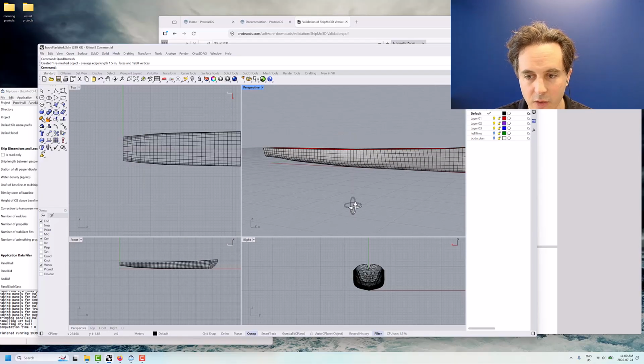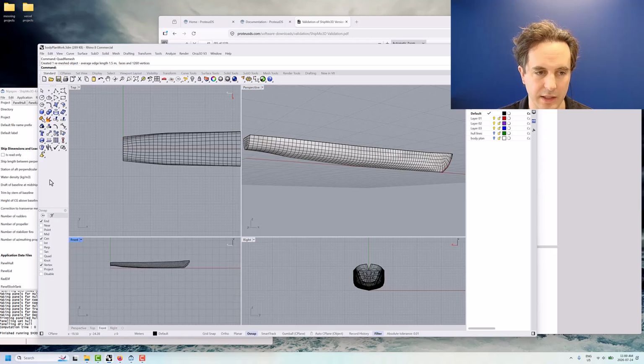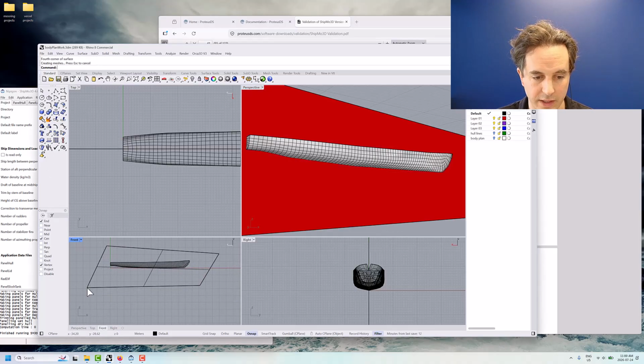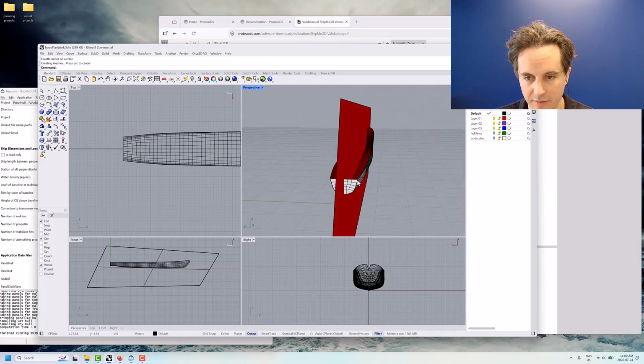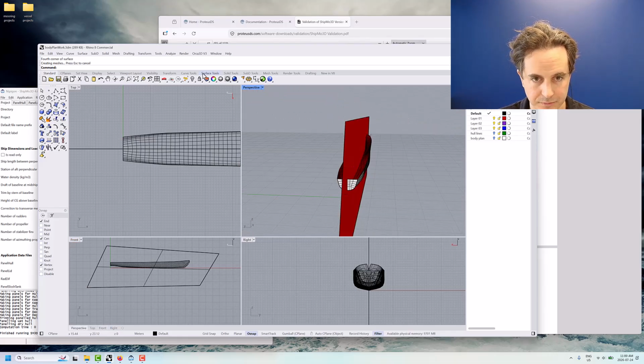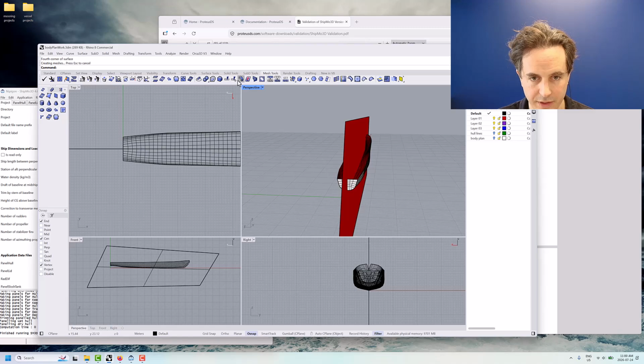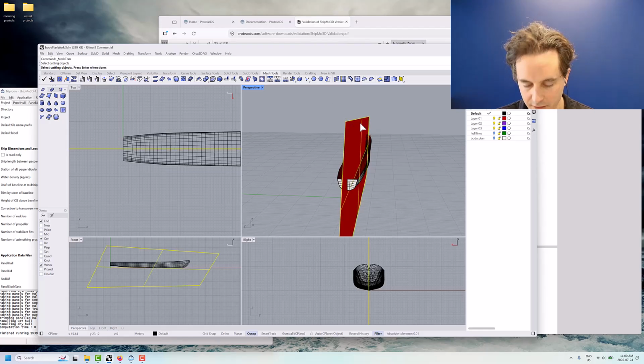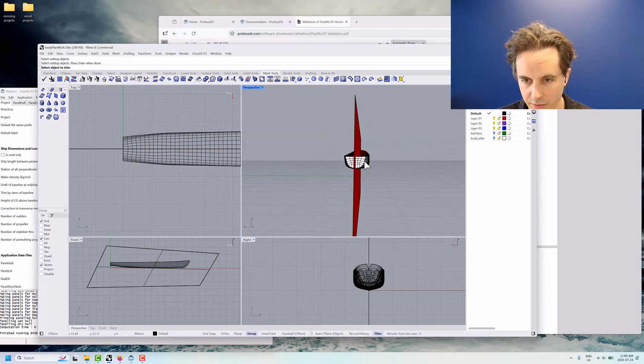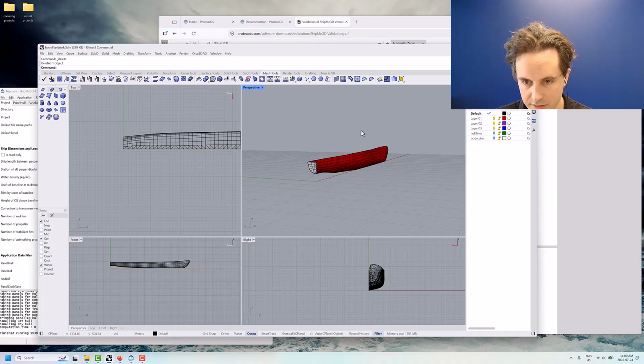So now what we do is we apply a trimming action here. And this for sure will guarantee that we have all vertices in without any negative components crossing the Y. So we'll go mesh trim, select cutting objects here, and we're going to trim off that portion. Okay, all done. We'll delete that.